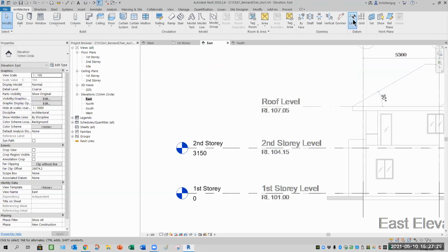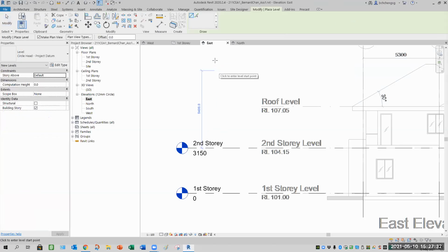By selecting the command, as I said before, here you will see this area is what we call your contextual ribbon, meaning the divider on your left side is all your modify tools. The one on your right is for creating your level. So how you want to place your level, you see it says line, meaning you draw it yourself. For creating a new level without any reference, that is okay, when you type the level you require, because you can see there's a tracking.